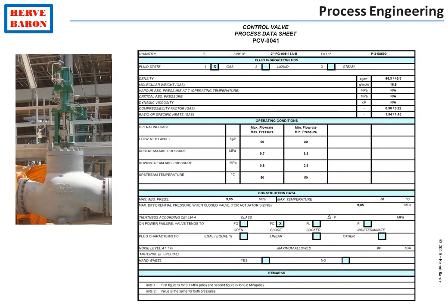The process datasheet of a control valve indicates the extreme operating conditions for the valve, so that the valve vendor can select the proper size so that the valve will effectively control over the full operating range. Usually that means that the valve is not less than 20% open and not more than 80% open. 20% to 80% is the effective valve control range.